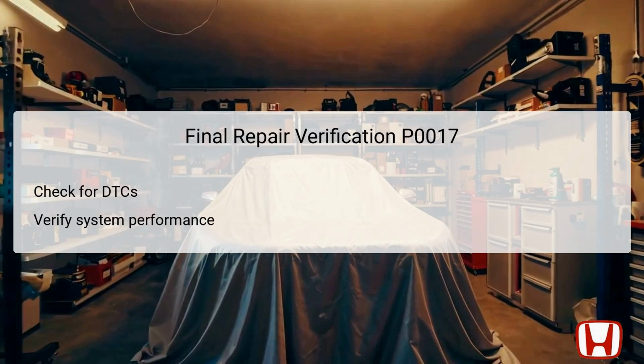After completing all troubleshooting steps for DTC P0017, it is crucial to conduct a final verification of repairs made. Begin by scanning for any lingering diagnostic trouble codes, DTCs, to ensure that P0017 or any other related codes do not reappear. This examination is essential in confirming that the system is functioning correctly post-repair.